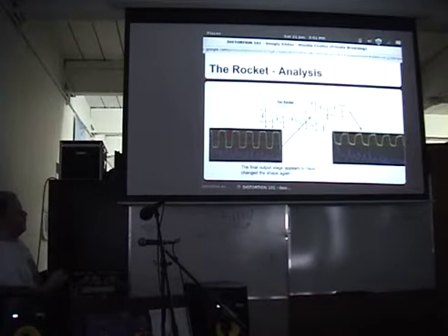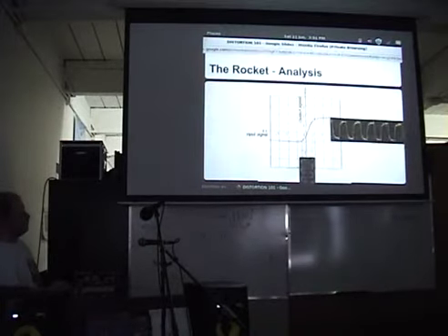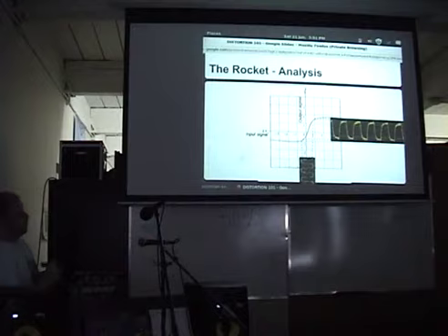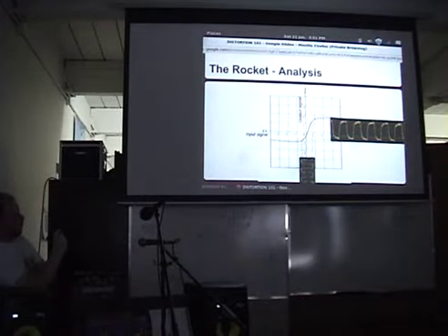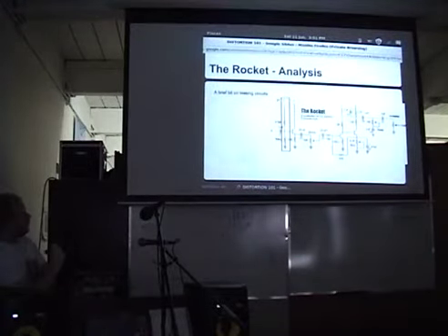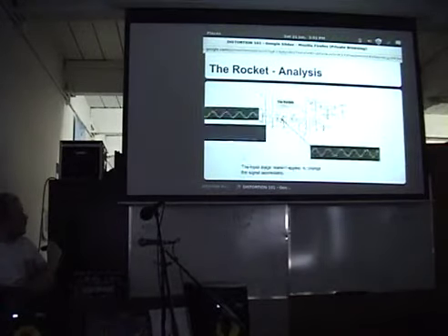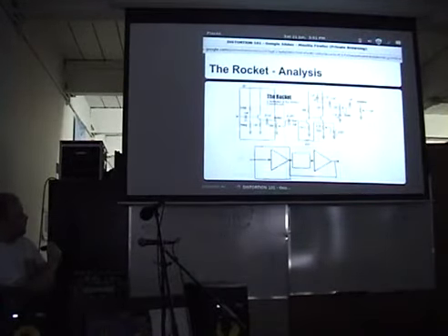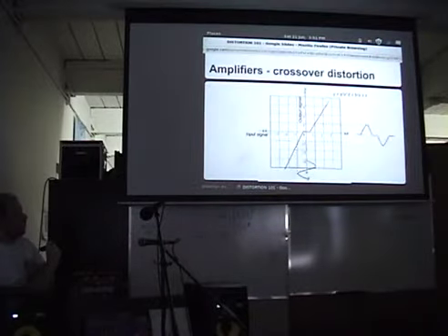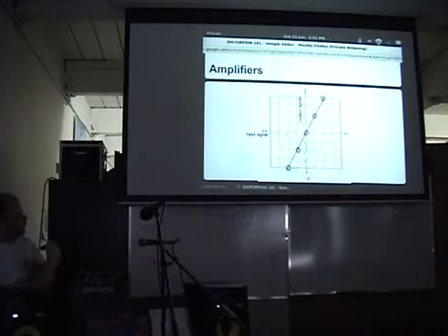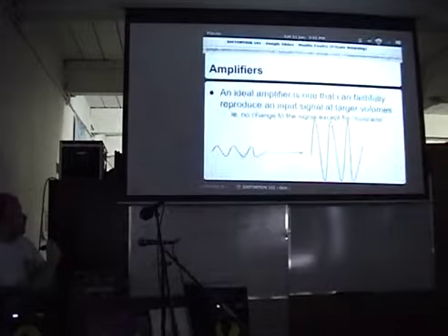You can see these are some nice flattened tops, and it's smushing them out a bit there. So you might surmise from these rounded corners that there's some kind of rounding going on in your transfer function. I'll touch on that more later, but to make really sharp edges requires a lot of high frequency content.